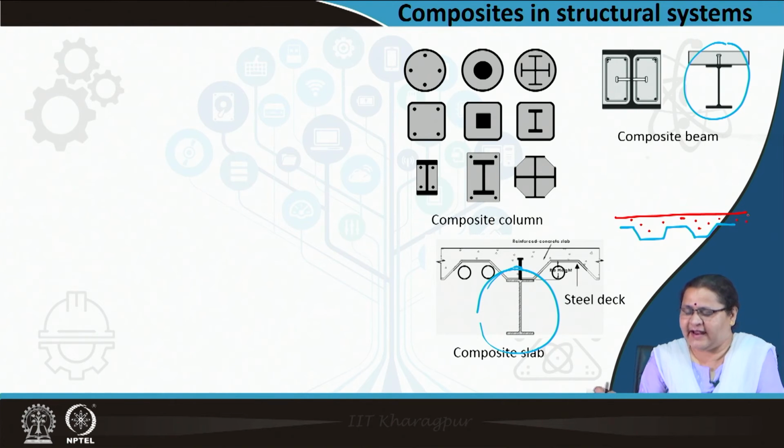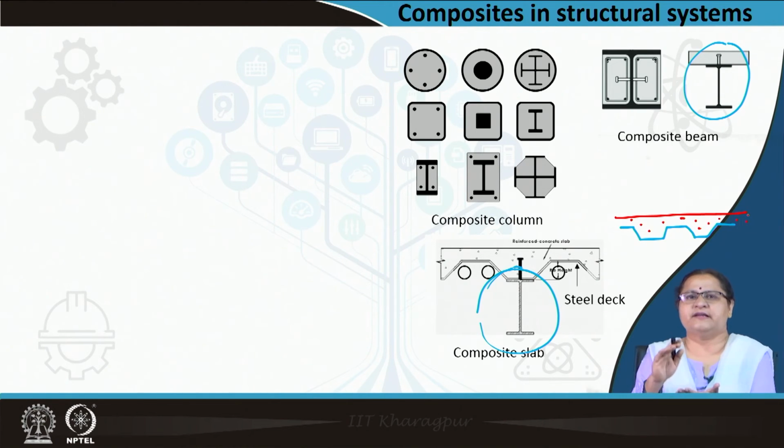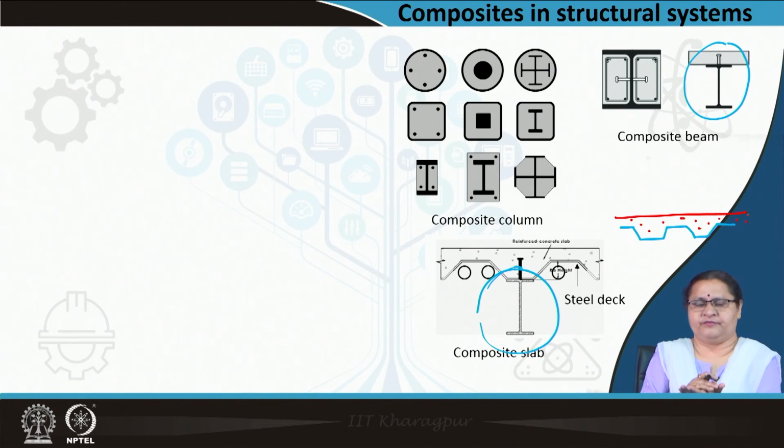So you get a flat surface on top of which you can walk, but what is gained? You are not using reinforcement at intervals. Rather, you have used an entire profile which has reduced the slab depth very drastically. So what have you gained? You have gained that loss of depth due to the entire thick slab. What more have you gained?